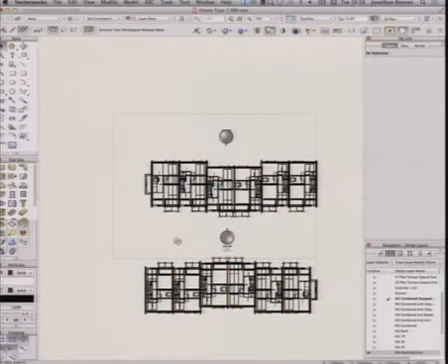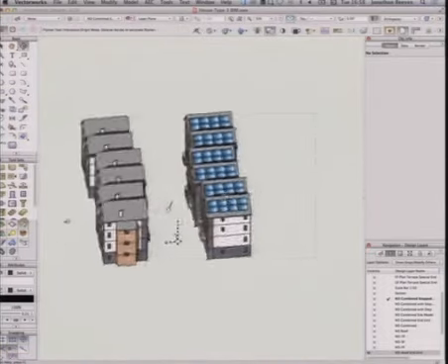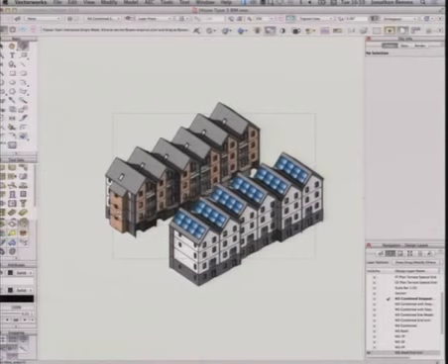And the reason for that is the information is just repeated a few times. So it gives me flexibility to try something out. I know that if I edit one layer back in the design layer, those changes will propagate through to this design layer. So design layer viewports, in essence, are a very useful tool for designing.